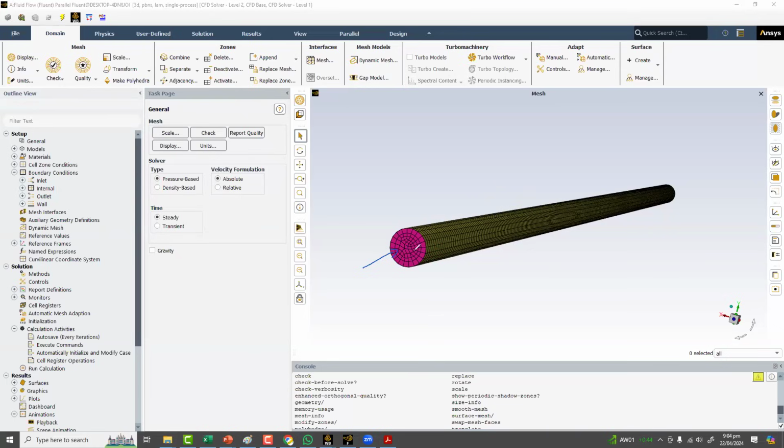But right now, I'm just finding out that when the pipe is flowing, it is going to give this much flow rate to the other side. So I'm just finding out that, okay, it is providing that much flow rate or not. In that case, I will not go with the transient case. I'm not interested in how the flow is evolving to this final state. So I will not go for the transient case here.